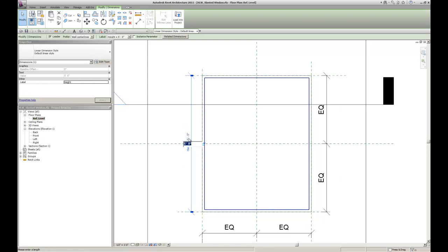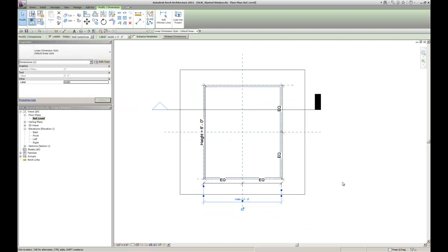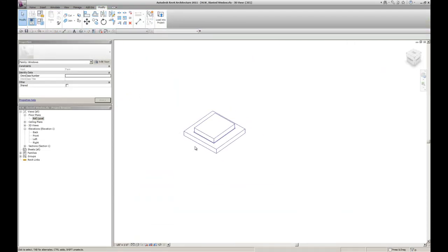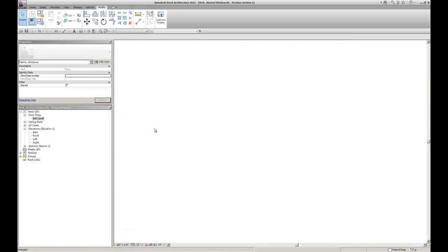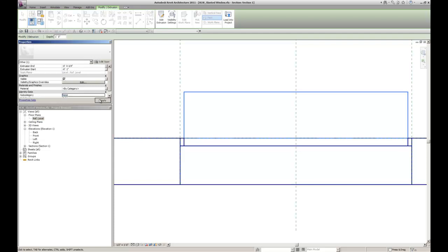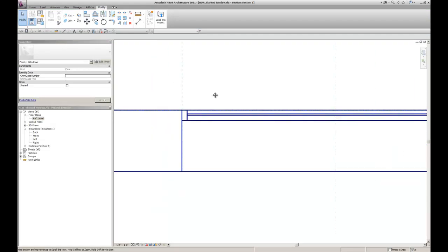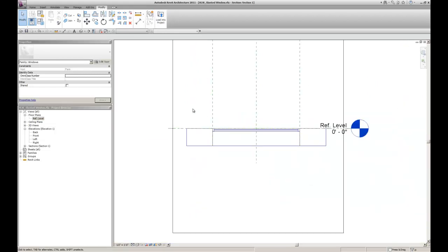I'm just going to test quickly to make sure it flexes properly. It looks pretty good. Check this dimension. Looks pretty good. You know, we've got a nicely flexing window, but we need to now adjust the height of our glazing. So here I'll grab this model glazing. I'm going to set it to extrusion start to -1 inch and extrusion end to -3/4 of an inch. Now I just have a nice little piece of 1/4 inch glass. Probably a little smaller than what we would usually use, but just an example.